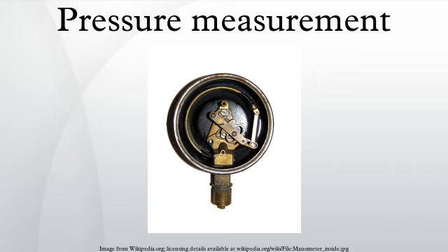Calibration: pressure gauges are either direct or indirect reading. Hydrostatic and elastic gauges measure pressure directly influenced by force exerted on the surface by incident particle flux, and are called direct reading gauges. Thermal and ionization gauges read pressure indirectly by measuring a gas property that changes in a predictable manner with gas density. Indirect measurements are susceptible to more errors than direct measurements. Dead weight tester, McLeod, mass spec plus ionization, dynamic transients.